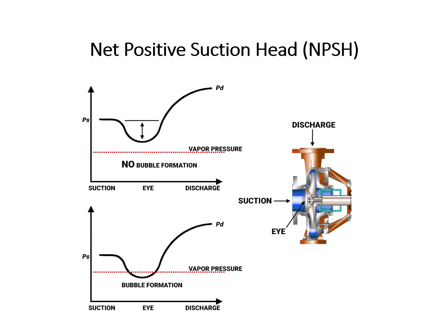So we can say in other words that cavitation happens when the net positive suction head available is less than the required. The required net positive suction head is what will prevent the pressure from reaching the vapor pressure. If your available is less, you are at risk of vapor bubbles forming and collapsing inside the pump, and noise, vibration, pitting, and pump damage will eventually happen.